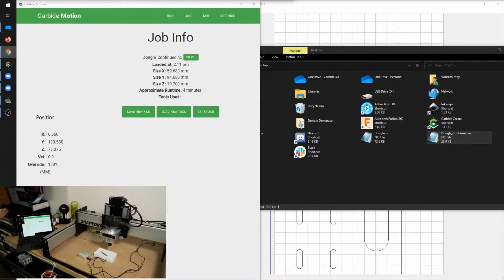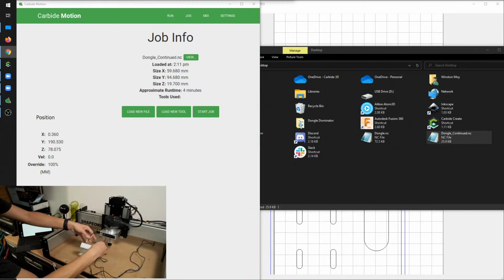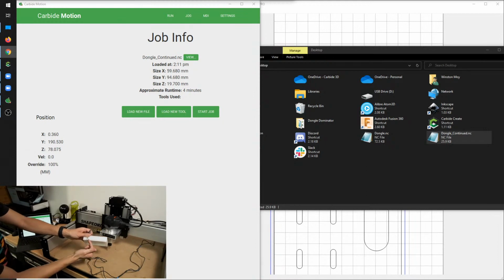First, you should isolate the wood with mineral oil. Depending on what you're cutting, potentially, but I don't know what the context is for that. How to have an up-down compression bit so you get the best of both worlds, clean surface and deep removal. I don't think I have one here. So basically, a compression or up-down end mill has up-cutting flutes at the bottom and down-cutting flutes at the top, so that as you go through material, you're pulling the bottom fibers up and you're pushing the top fibers down.